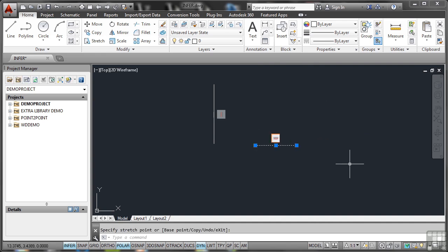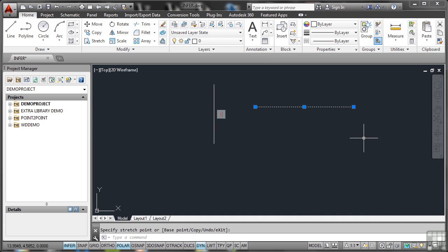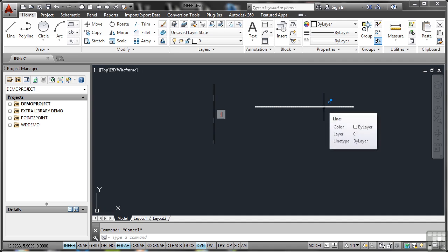Now, I've still got that horizontal line selected. If I hover over the little icon and close it there, you'd think that that would lose the constraint, wouldn't you? Click on the grip. No. All that does is it hides the constraint bar for that particular line. So there's still a constraint on there. You can see when I hover over it, you get that funny little blue symbol there saying that it's constrained. So these constraints are very useful if you want your circuitry, let's say your wiring, to remain horizontal or vertical.